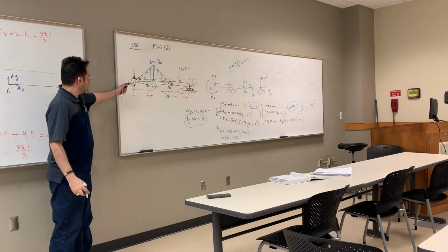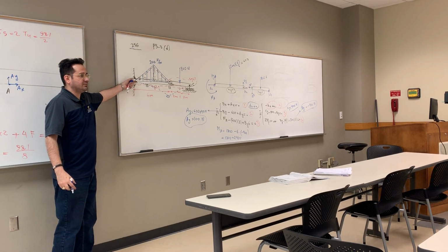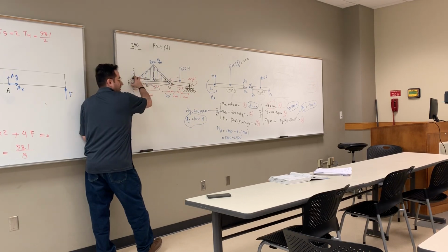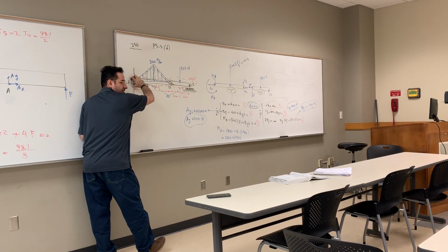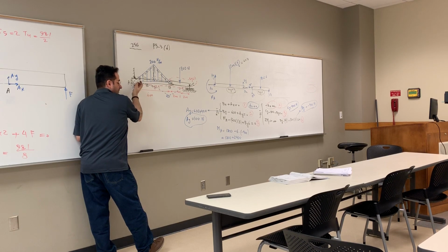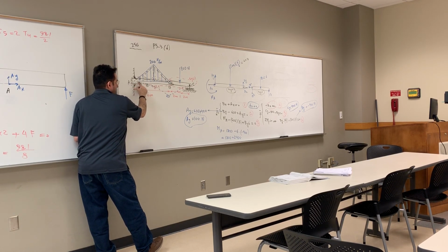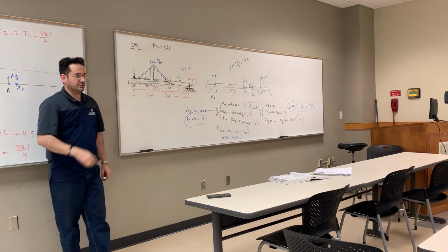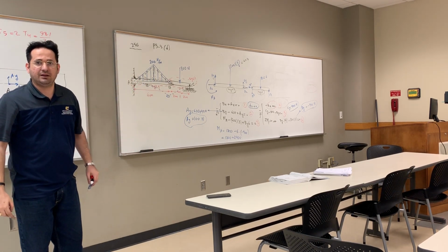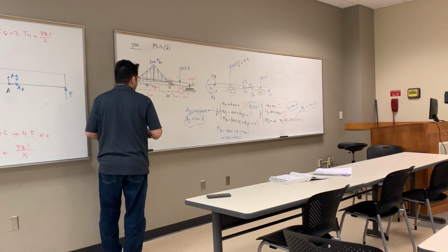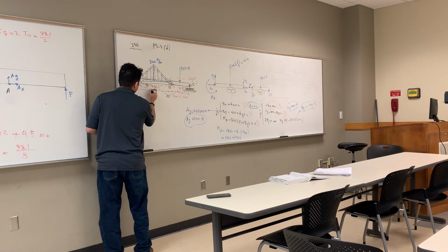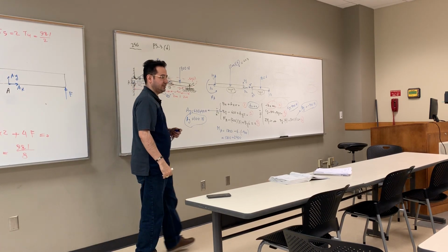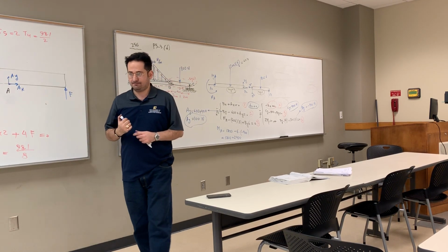The slope is zero here because you have a moment that is preventing rotation, right? So this is like this and then goes on down. The slope is zero because they really at the wall. If you had a pin, then this would go like this, because you can easily rotate over that point. See that?